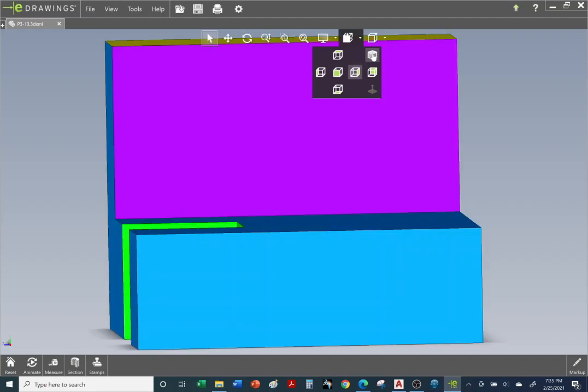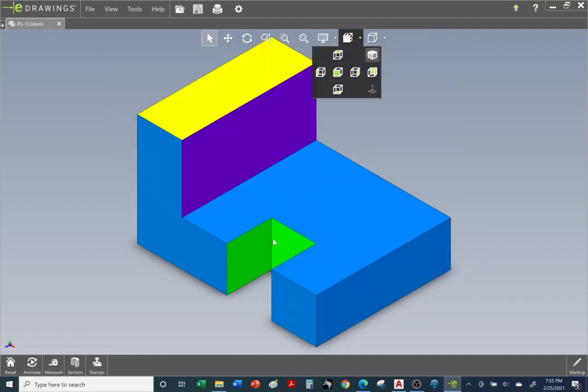If we go back to isometric view, there's this pocket here, right? That we cannot see if we're standing over here on the right. So again, think of Jack's mugshot. Here's the front view if you're standing here, staring at Jack. And go over to the right side. If you're standing over here on this side of the building, you cannot see this pocket here. So we're going to use a red line to represent the depth of this pocket here.